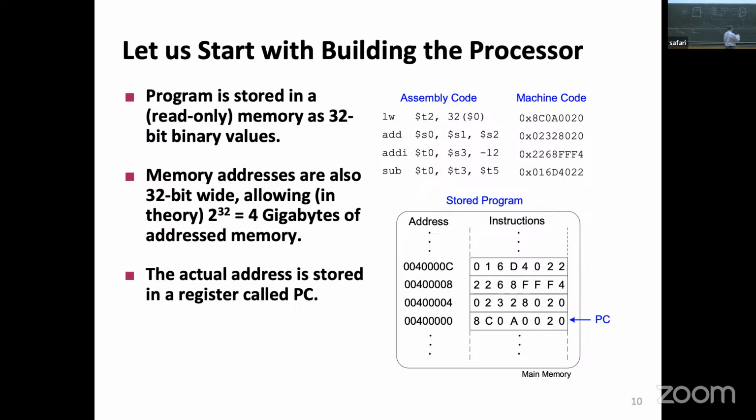And then at some point, I have my ALU operation. Now, the ALU operation could depend on what the function is in my instruction, right? So I could do addition, I could do subtraction, I could do many different things. So one of those operations will be picked up from the function bits. So the function tells us what to do. At the moment, I don't have that many more control signals, but as we try to implement more and more instructions, we will fill this thing and we will have a bunch of different control signals. And my very, very dear multiplexers will start filling this drawing.